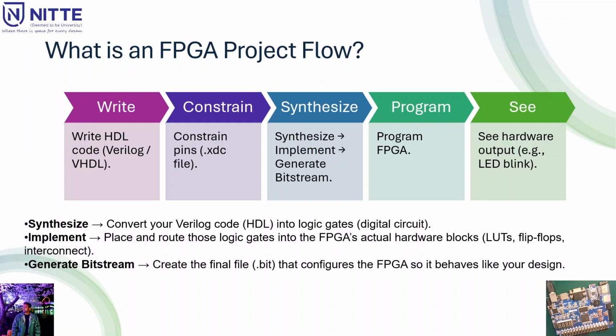Once implementation is done, we need to generate the bitstream. The bitstream is the file we finally dump into the FPGA board. If the bitstream is ready, then we are ready to program the FPGA, and later we can see the hardware. All these things we are going to see in upcoming videos, hands-on, very practically, and you will come to know what I mean.